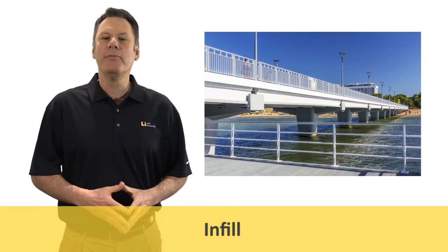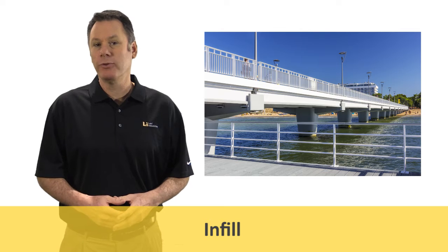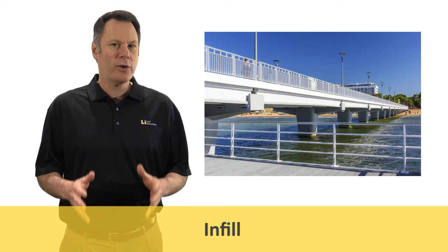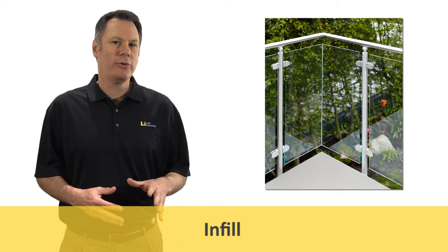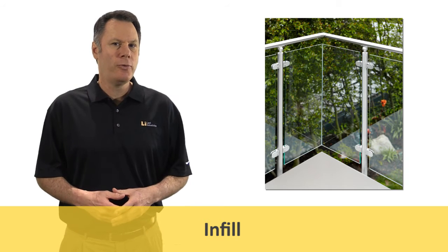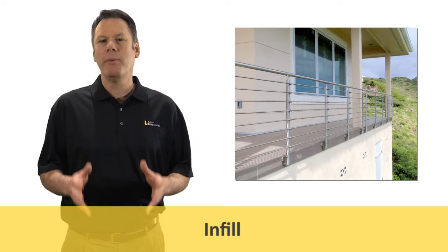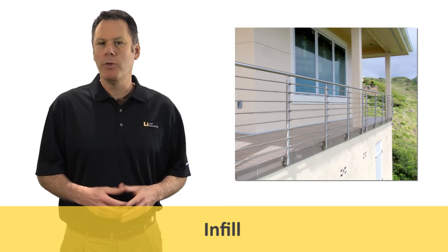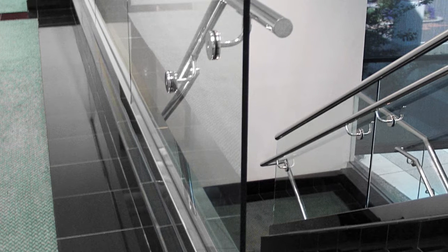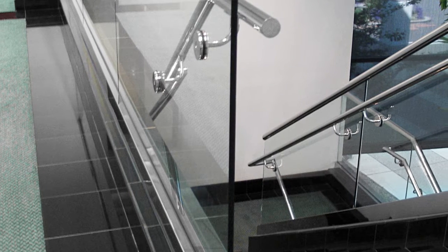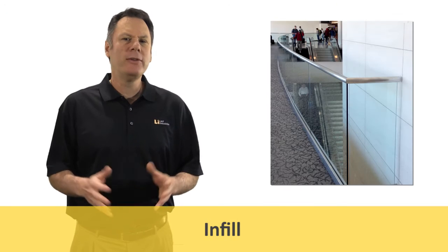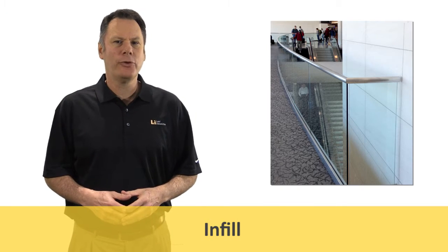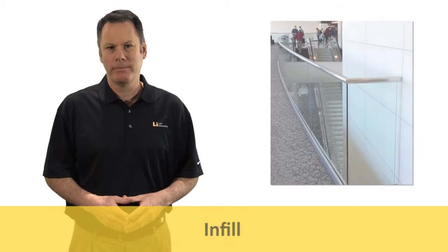Infill, a series of balusters with panels, mesh, or similar elements, serving as a structural and/or decorative element located between top and bottom rails and posts to serve the twofold purpose of protecting bodies from penetrating and falling through the baluster and panel infill areas, and providing a specified resistance to horizontal thrusts as are potentially encountered within the infill area. Infills should be designed in such a way as to deter climbing of the railing system.